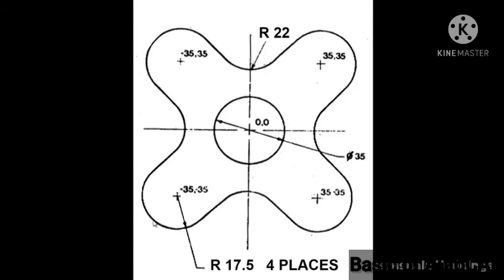Which will be this particular point, and we should give a value which is again lower than 52.5 so that this circle will be well within the screen. So I'll give say minus 60 as the lower left, and the upper right should obviously be 60, 60. So likewise, by setting the lower left at minus and upper right at plus, you could bring all the 4 quadrants within the screen. So that is how the limit for this particular figure is set.